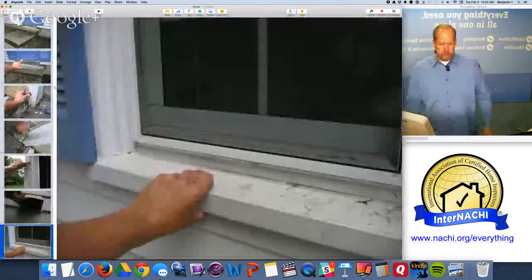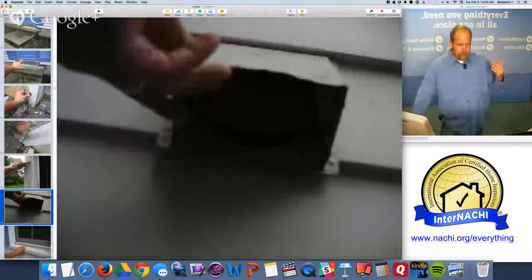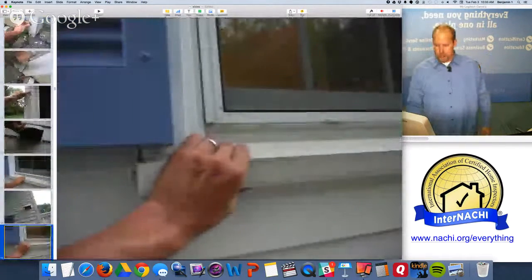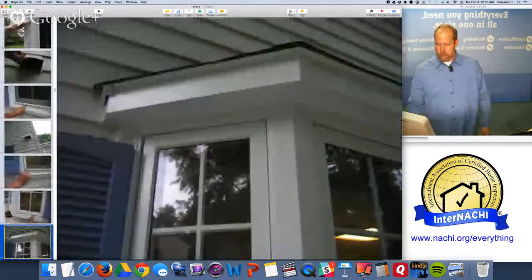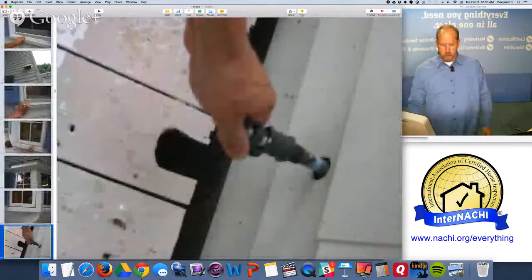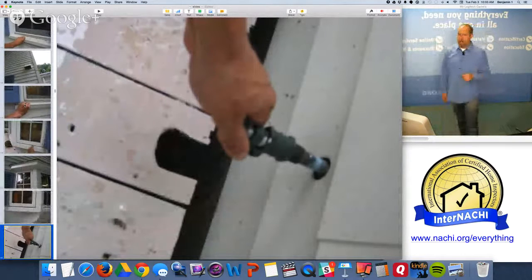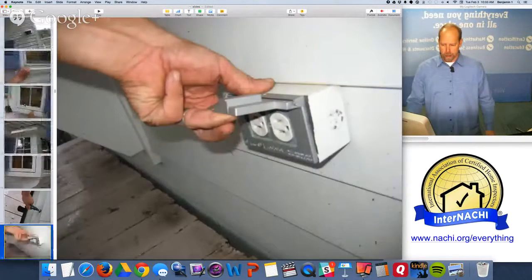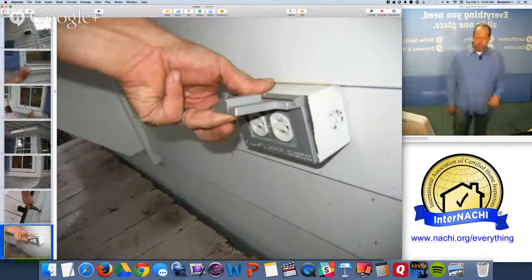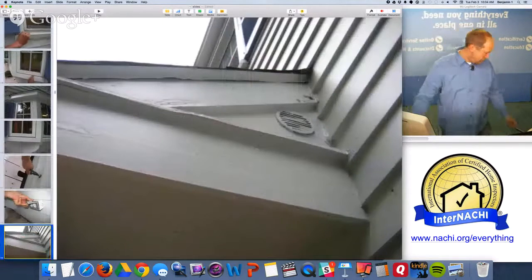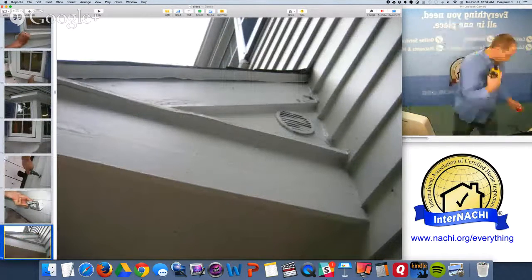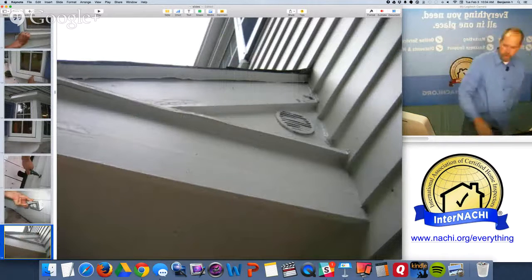Dryer exhaust, keep that in mind. Is it a bathroom or dryer exhaust? Every mechanical exhaust should be going outside. Window sills, trim boards, water faucets. This is a cold climate, so every spigot on the outside should be a frost-free hose bib spigot. Every receptacle on the outside should be GFCI protected. And we went over in the beginning of the course on how to test those, or the tools that help you test them. Very easy to do.